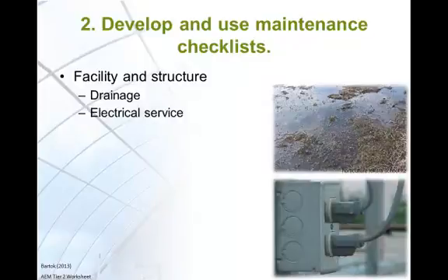Inspect electrical wiring systems for corroded parts and faulty insulation. Ensure that outlets are not overloaded with too many plugs on a single power strip. Proper grounding is important in the greenhouse as it is a wet environment. For more information on electric safety, see the Greenhouse Safety Module.